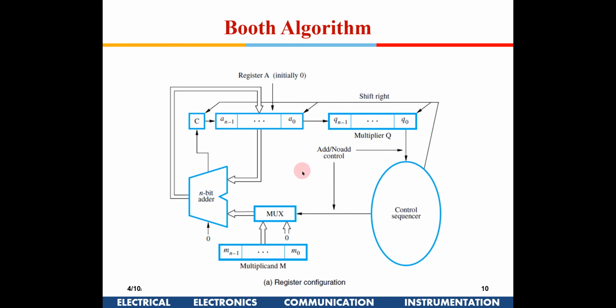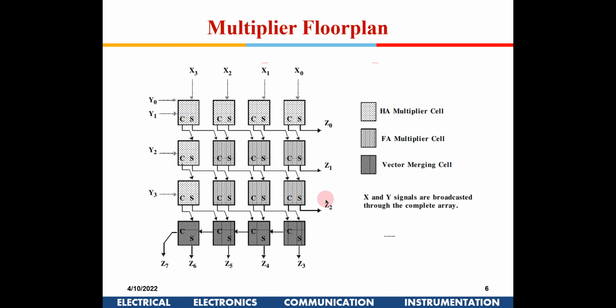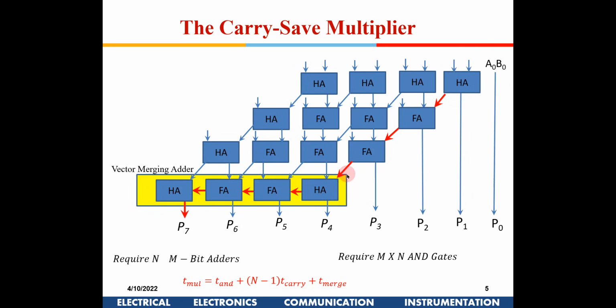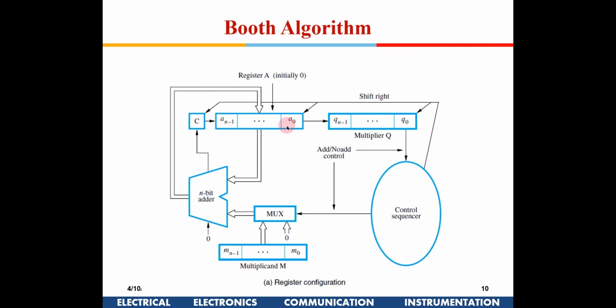So when we compare this circuit, in the earlier days, when circuits were operating at very low clock frequencies, this was an okay option, because for a 64-bit multiplier, it will require 64 clocks, and if your clock is only a few megahertz, then it will take that much more time for the result to come.